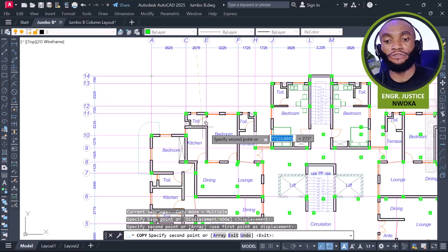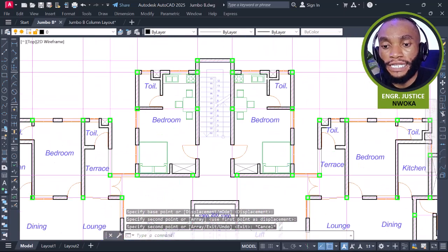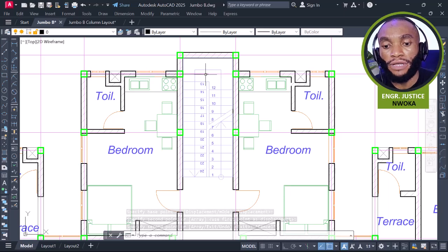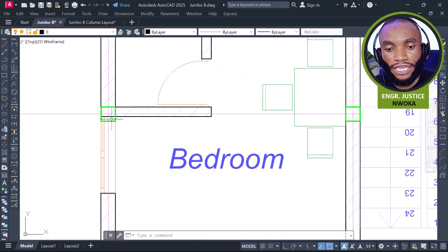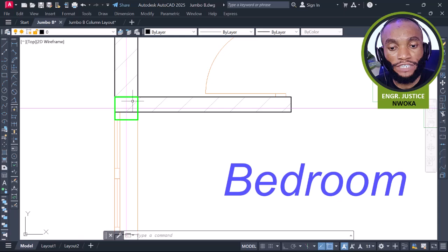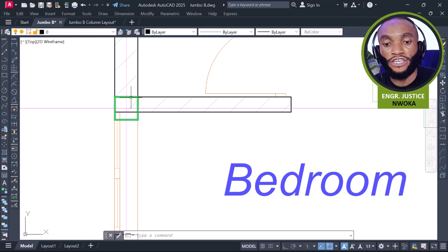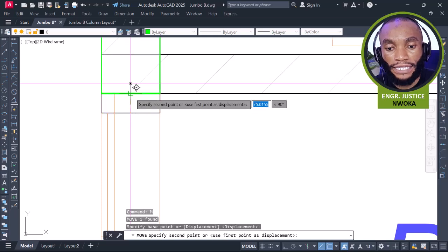By doing this, let me now look at what the guy placed on his columns. Now you can see how he placed his columns. Basically this column here is already flying, touching the window, which I believe I'll have to shift back. Okay, so this is not correct. So with this, I'll shift this backward here, and then keep this here.